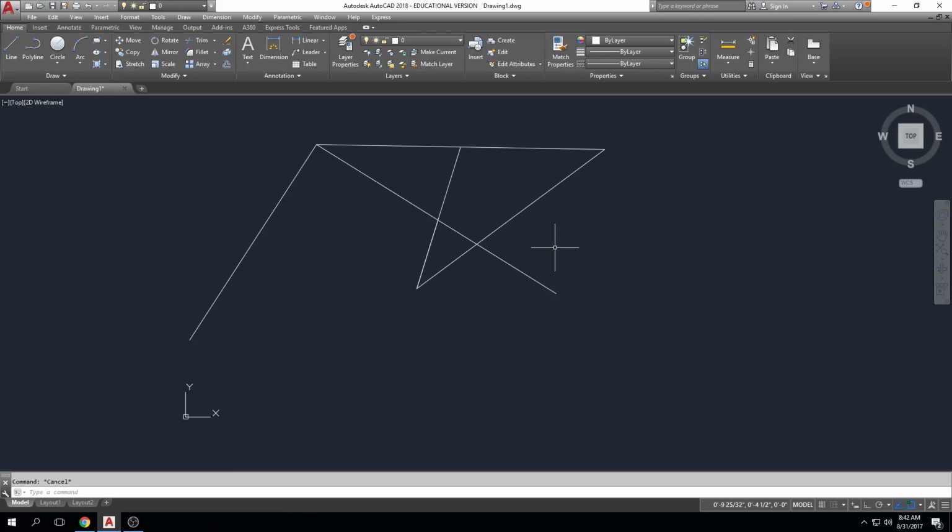They help you find that exact point on a line so you don't have lines crossing over one another, not quite reaching one another, not quite at the midpoint, right? They just help you be more precise with your drawing, okay? We've talked about ortho a little bit right here. Ortho will help you create exactly straight lines. So you'll see me turning ortho on and off all the time, right?